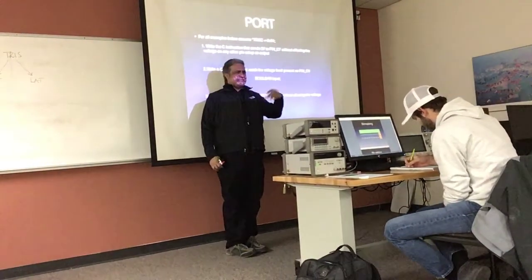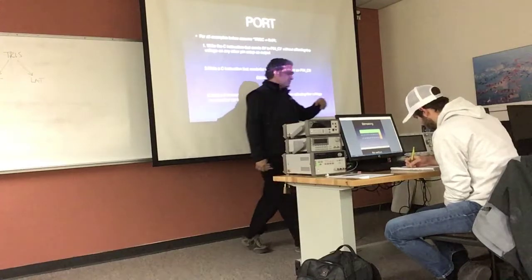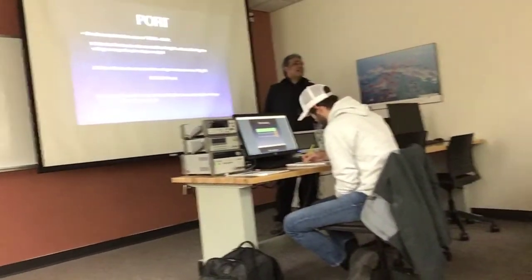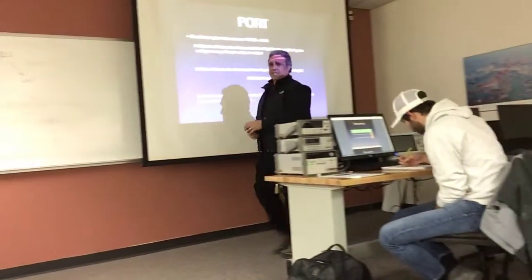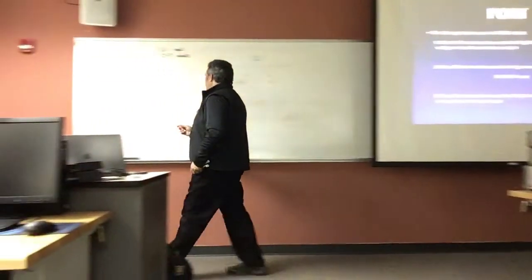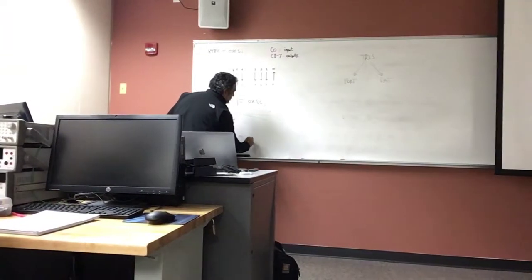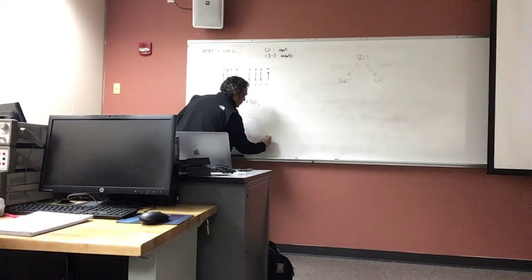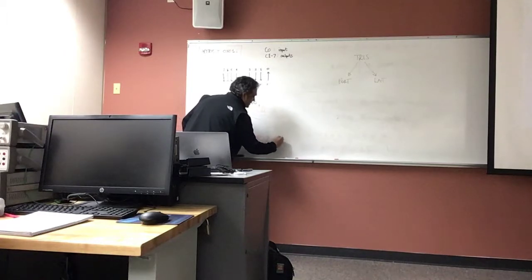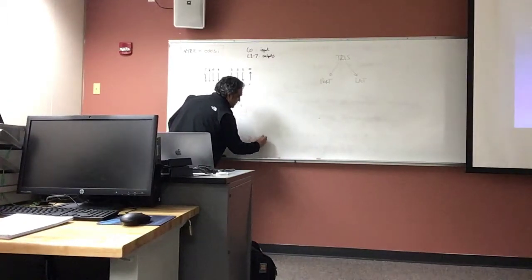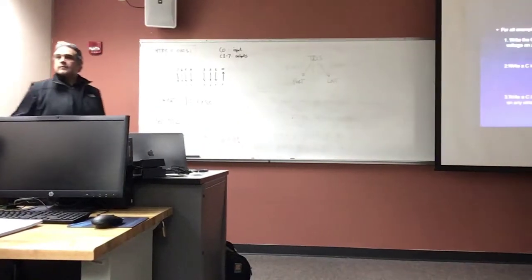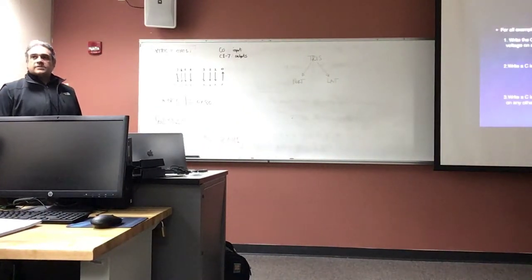It exists in CCS, the Code Composer Studio has the Boolean data type. It's just a single bit. That's all it is, right? So we're going to do input equals, and then I'm going to use the port C, and then I'm going to read the least significant bit. Right? See that?